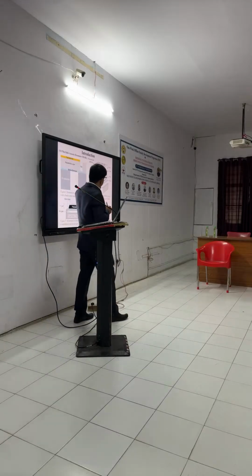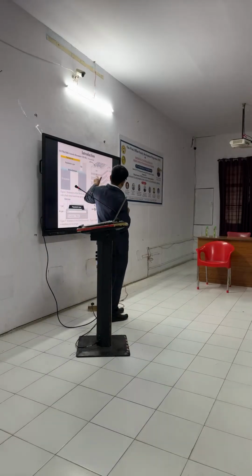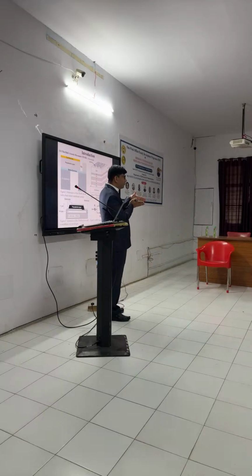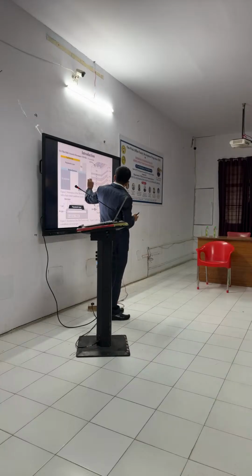In the second structure, instead of this air cavity, we can use a reflector. So what is basically a reflector? A reflector is a combination of two layers that have a very high acoustic impedance ratio. Here I have an oxide and tungsten. Both these layers have different acoustic impedance. If that acoustic impedance ratio is very high, then we require fewer mirrors. So here we use one mirror, two mirrors and three mirrors. Here we use three mirrors to confine our acoustic signal.